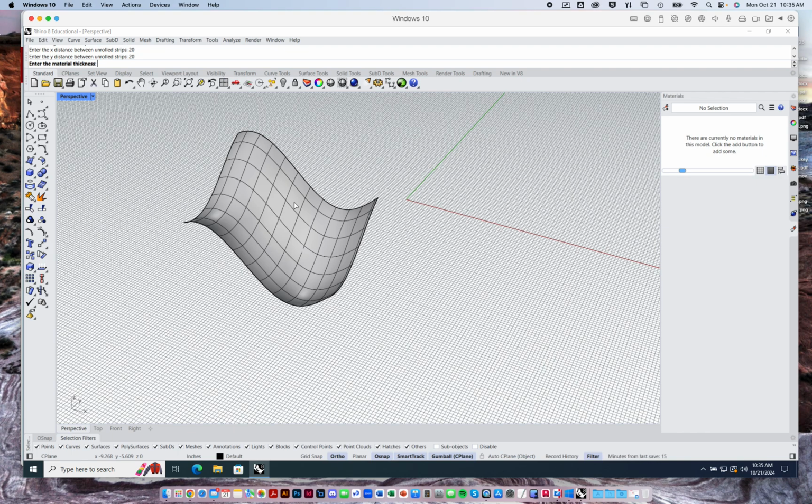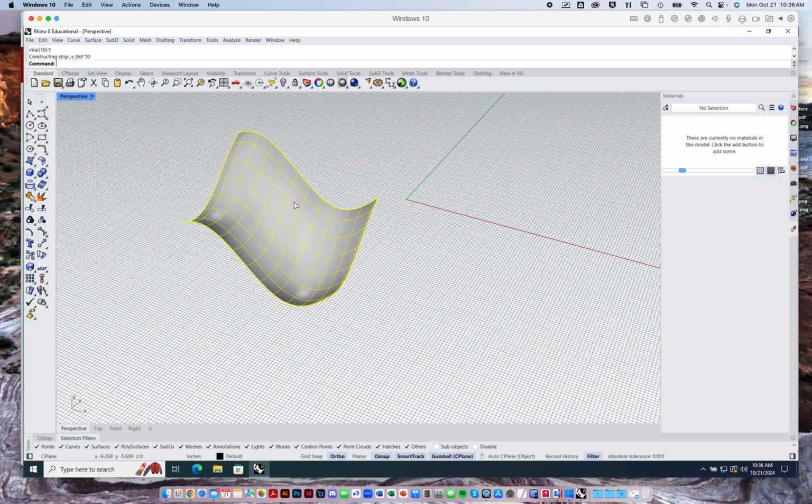Sometimes it's 0.030, right? If you buy material and then you bring it in, what I recommend doing before you run this script again is take it to Kyle over in the laser cutter room and say, hi, can you get your digital micrometer out and digital calipers, and we'll just measure the thickness of this really precise and make sure if it's 0.040 or 0.032 or something like that, right? Be very precise. So I'll say 0.03 and just hit enter.